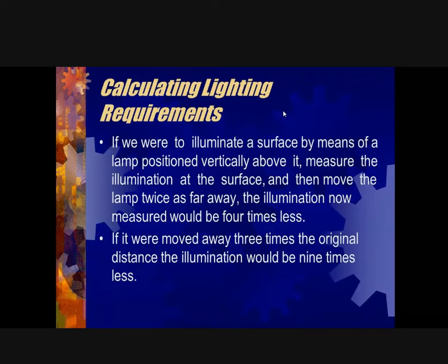So it's not just a little bit less, it's actually 4 times less. Say in a building they raise the roof, and the lights are now positioned higher. What will happen is that if the lights are not redesigned, you're going to have less light reaching the surface, right?